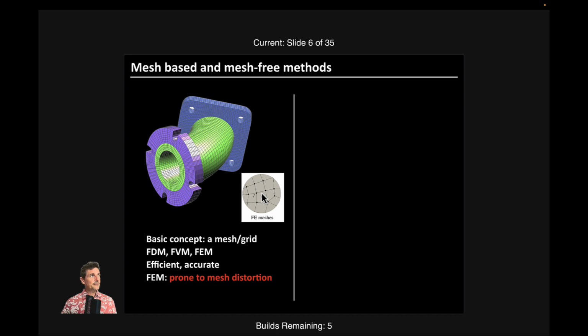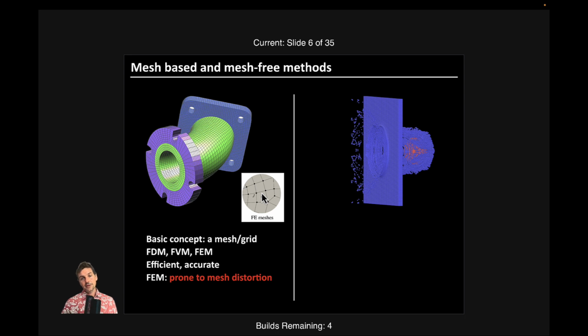For example, strain smoothing stabilization. This is something that, if you are interested, I can talk about. Or mesh-free methods, which are less sensitive to distortion of the mesh. I say less sensitive because my own experience of moving least squares, element-free Galerkin, for example, is that it is quite sensitive, actually, to point placement. And this is also what we see in finite difference methods, where if we have suboptimal point placement, things go quite bad, I have to say. Okay, meaning that we can get results that are completely wrong, right? I mean, at least not convergent.